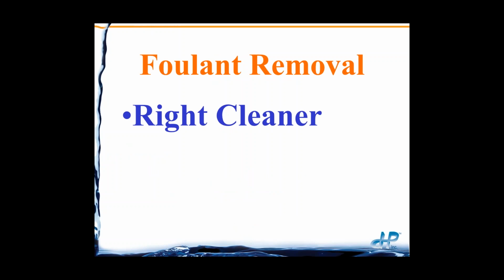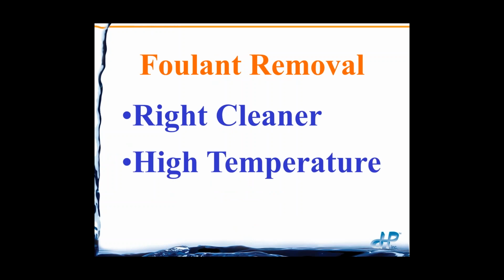As far as a general procedure, we need to use the right cleaner. So if we're doing silica, organics or bio, we're using a high pH cleaner. A high temperature, again, chemical reaction rates increase, plus with biofilms, this may loosen them up, thin them out.